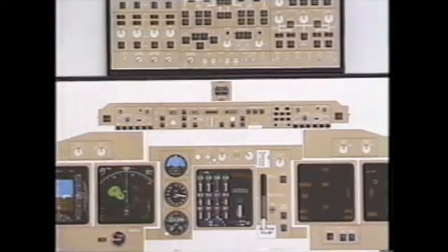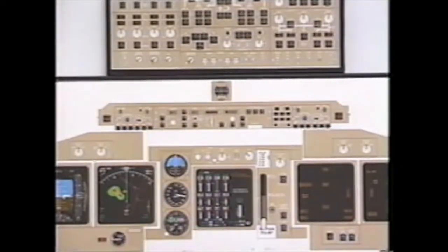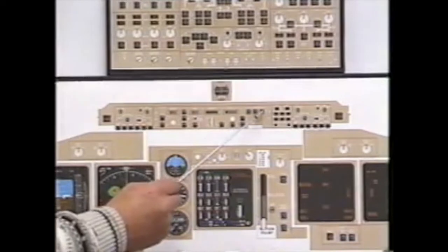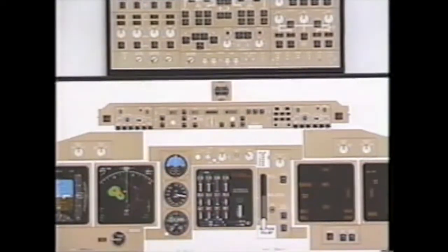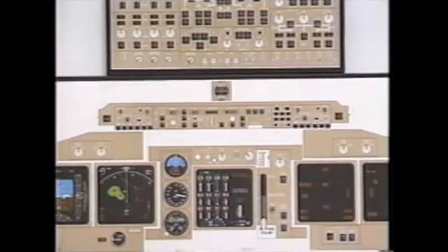The left autopilot uses hydraulic system number 3, the left IRS, and AC bus 3. The center autopilot uses hydraulic system number 1, the center IRS, and AC bus number 1. The right autopilot uses hydraulic system number 2, IRS right, and AC bus number 2. Again, the gauge left, center, or right is always 3, 1, 2. Underlined numbers with regards to autopilots.